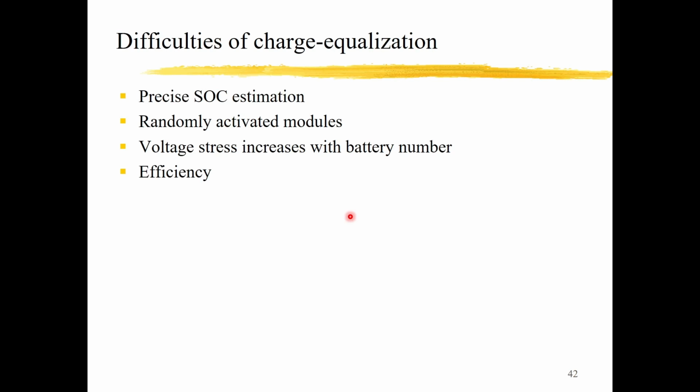However, the charge equalization function can only be partly achieved by the BMS IC, and especially the BMS IC can only achieve the balance inside the module. But for today's battery pack, there are several modules, and we also have to achieve the charge equalization between the modules.